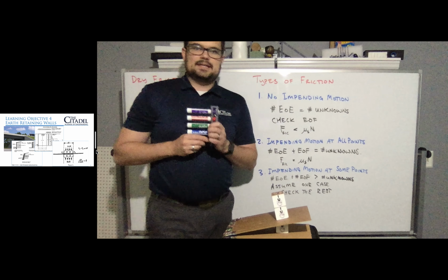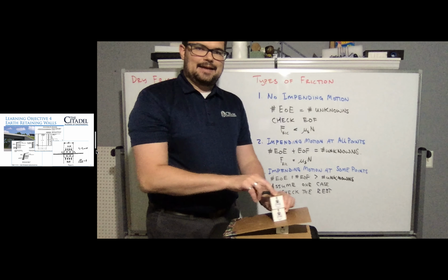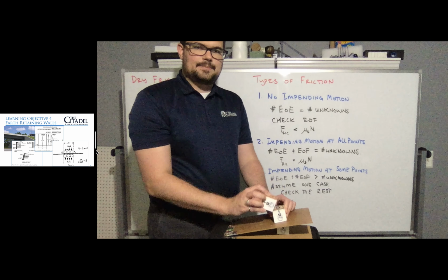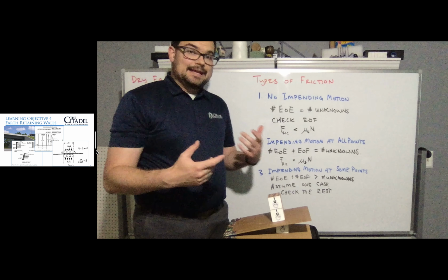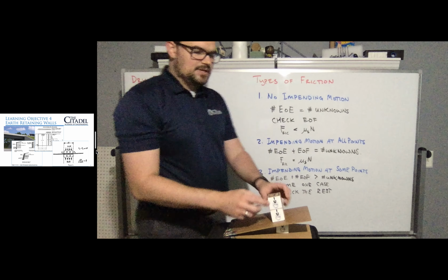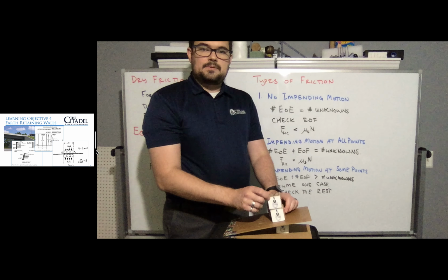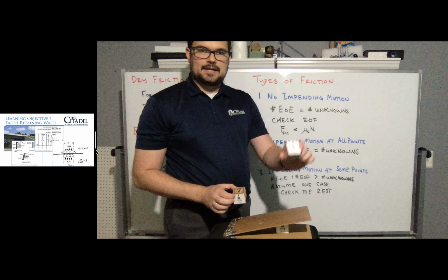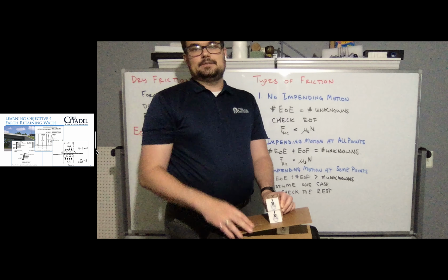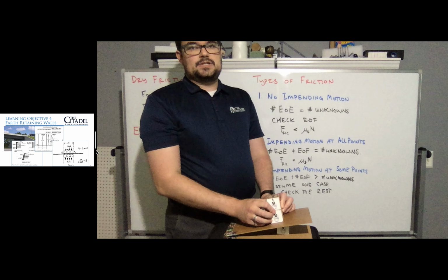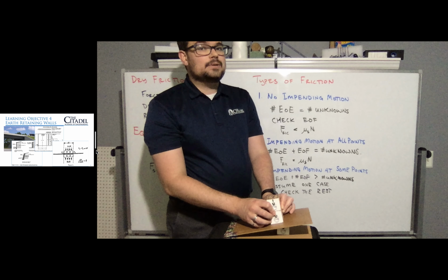So we could say, of the different ways this could fail, I have a toppling case, I have the 2 sliding together, I have the 1 sliding off the top, and I suppose that could rotate off like so. Those are all potential options. I would make a guess, meaning set, say, the equation of friction between the blocks equal to 0, right? Do all my equilibrium equations. I'll have equations of equilibrium for this block and for this block. So that's up to 6 equations of equilibrium, plus the 2 toppling cases, plus the 2 equations of friction. So now I'm at 10 equations, except I only have 7 unknowns.